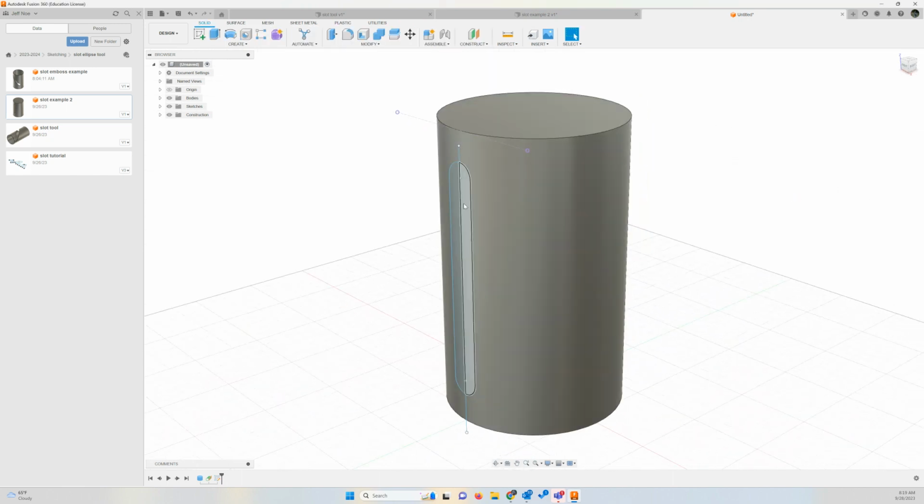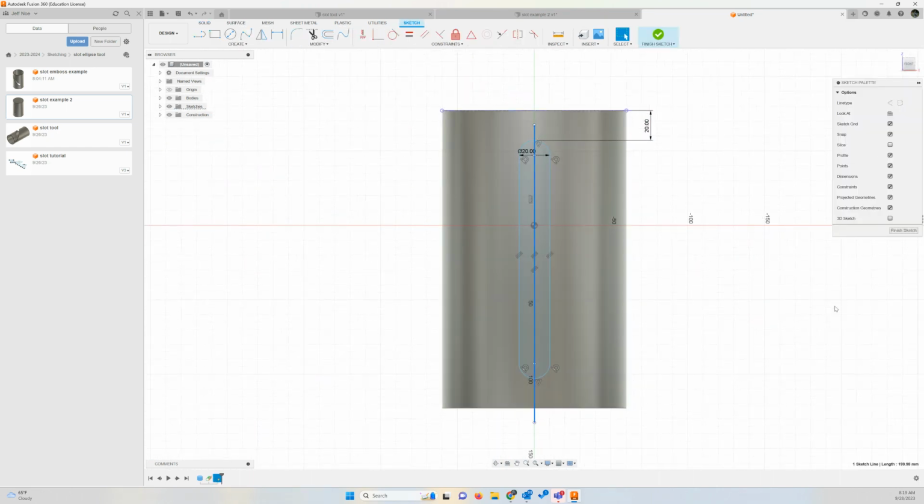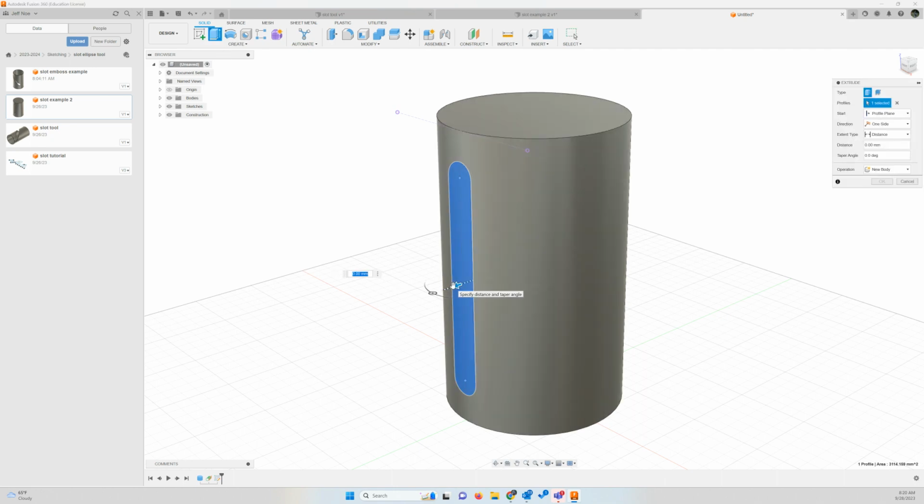All right, so now I must have toggled the construction line, so let's go back in and edit sketch, select my construction line, and let's just delete it. Hit the delete key. There we are. Finish sketch. Back to the home position. There I have my shape enclosed. One shape. Let's extrude. This has been messy, hasn't it? Drag it back through. Click OK.